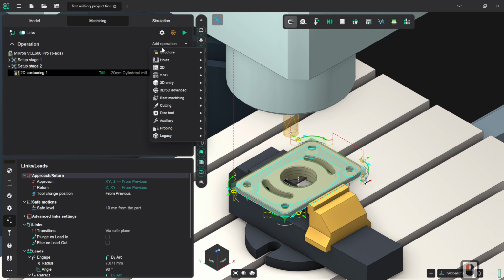You'll notice it says 24 and 22 instead of 0 down to -2. That's because it retains the depth values from the original setup, which is what I meant when it said it inherited those values from the first setup when we were implementing the setup stages. That 2mm is exactly the correct value that we need, so that's all good.